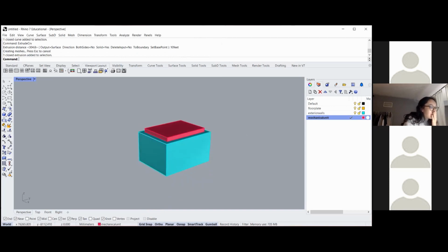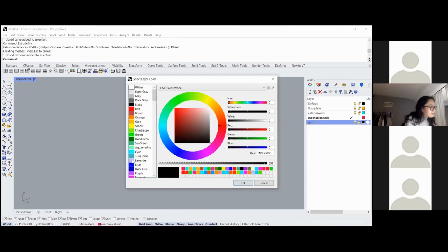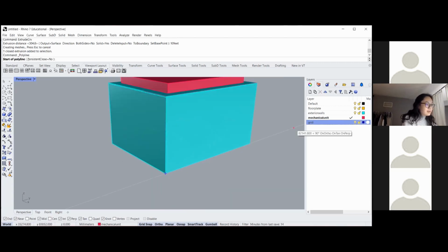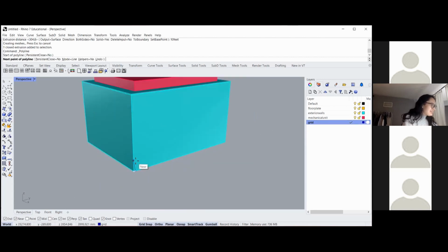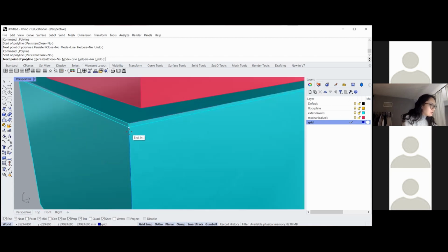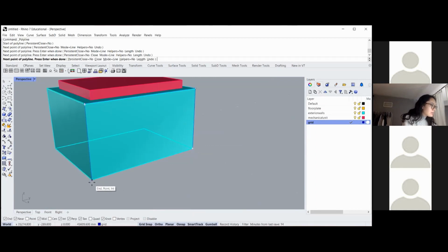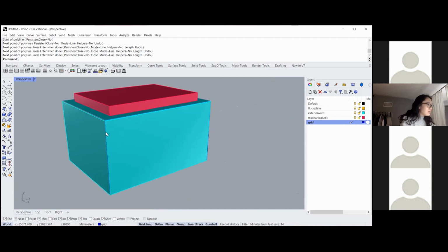So outside of the band, there's that grid that surrounds the windows. So we're going to go ahead and create that. What I'm going to do is create another layer called grid. And then make sure I'm on the right layer. And then I'm going to create a box or a rectangle so that I can set up my grid.